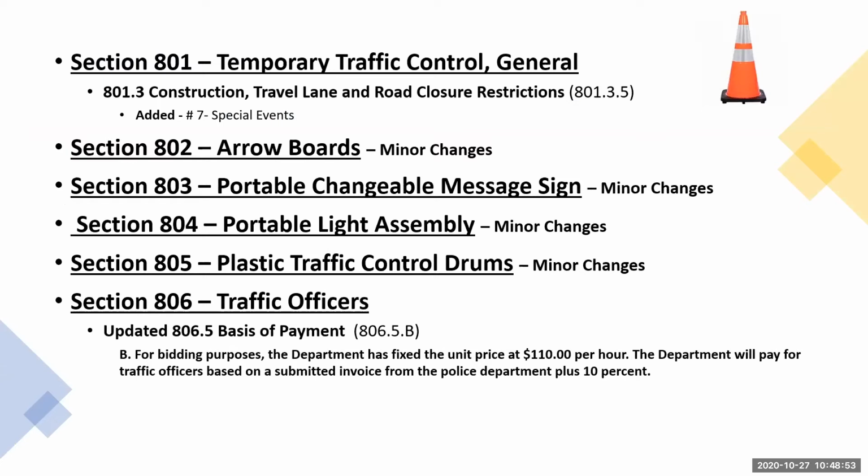Also in 801, there is reference to the approved products list again. And there is an approved products list for temporary traffic control devices. And if you open that file up on the website, you'll see, I think, 7 pages now. And it's related to anything that's considered a crash-worthy device, your drums, your sign stands, type 3 barricades, TMAs, temporary impact attenuators, those types of things. So make sure you pay close attention to those related to MASH compliance.